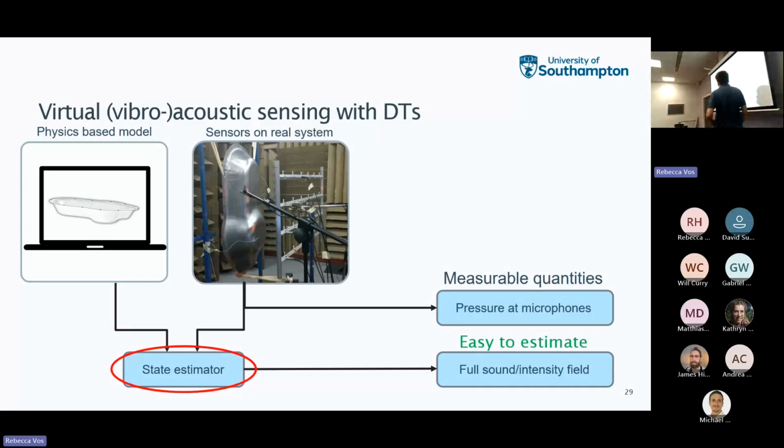For this particular application, we have a virtual model, which I will show you in a bit. And we did some measurements in the lab in a semi-anechoic room to get some data. So we basically have the data at these specific microphone locations, and we also placed some accelerometers, as you can see here on the structure.